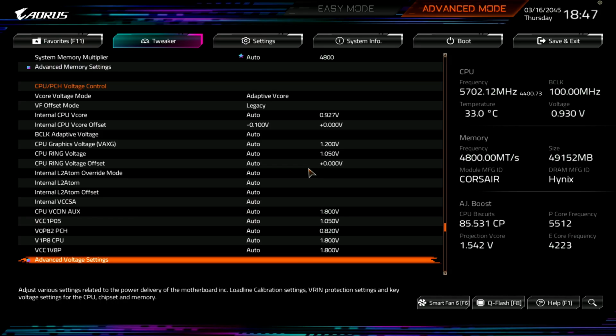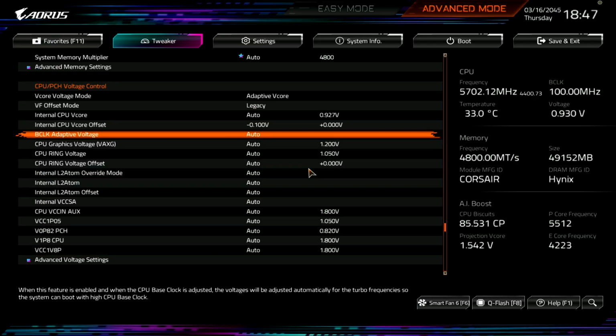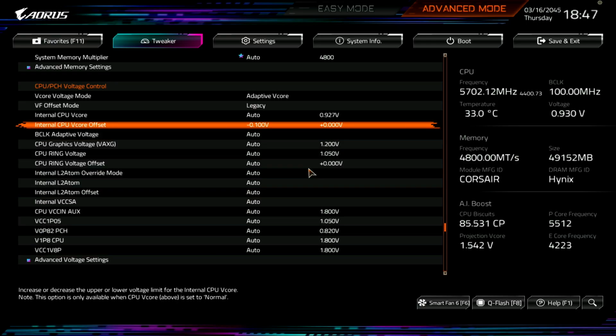Not the oscilloscope, because hooking up the oscilloscope to the die sense circuitry is generally not good. Actually, even hooking up the multimeter to the die sense circuitry is not ideal, but I've done that before, and it's less concerning than what happens with the oscilloscope.